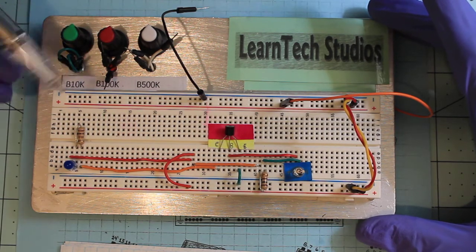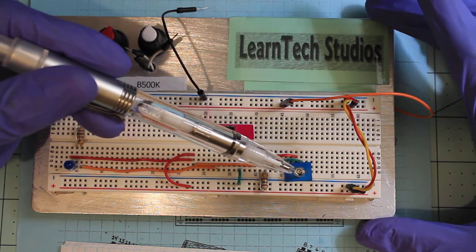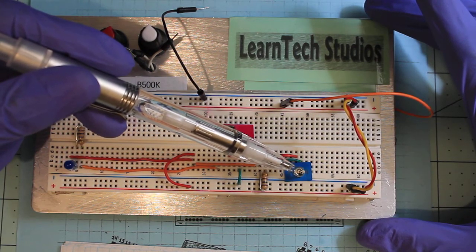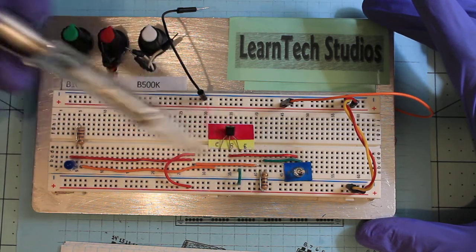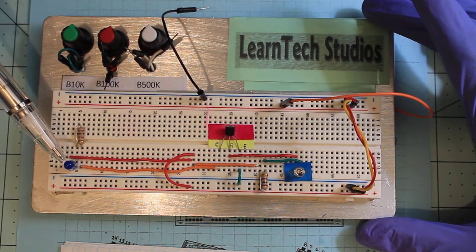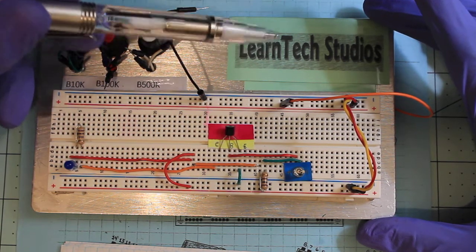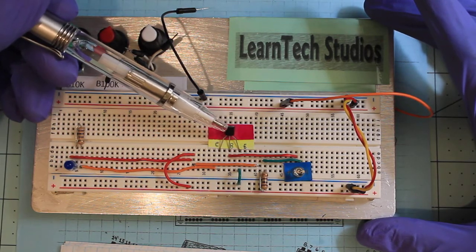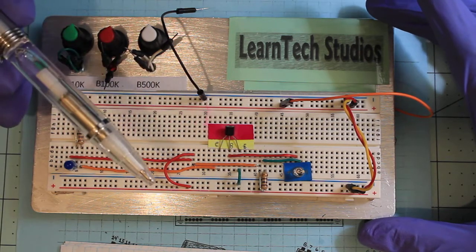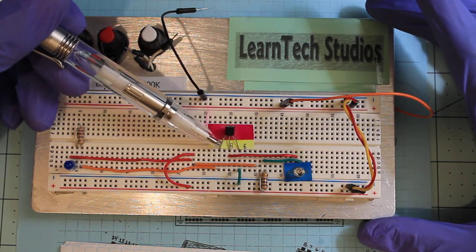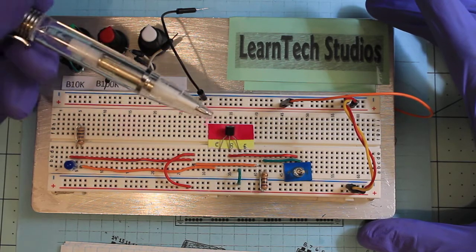In this circuit, we have a couple things to make this work. I'm going to show you how to make the LED, not the LED, sorry, the photodiode, complete the circuit and light this LED through a battery that's going to be connected. We're going to be using the NPN transistor as the electrical switch, you might say. You've got the C, B, E, collector, base, and emitter pins, of course.